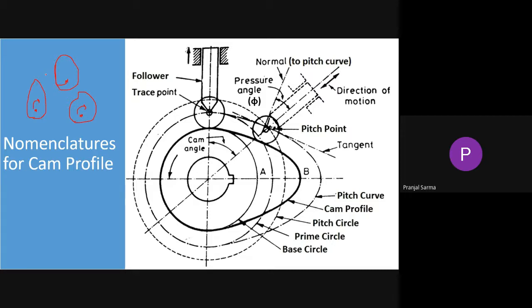For all of these cases, number one, number two, number three, if you follow those curves, that is the cam profile, and you can see the steepness is different. So the pressure angle gives you an indication of the steepness of the cam profile, and this angle is very important while designing the cam.